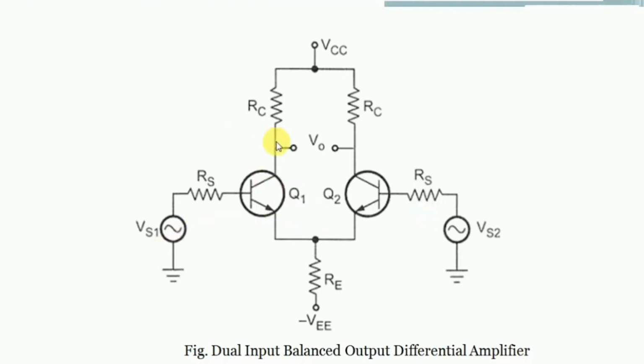That's why after obtaining the operating point values, we have to make sure whether the transistors Q1 and Q2 are in the active region or not. If they are in the active region, then we apply the analog signal to the circuit, in which it will perform correct amplification without loss of signal. For this circuit we have to obtain the DC equivalent circuit. After obtaining it, we perform KVL and KCL operations on the circuit in order to find the output current and output voltage.